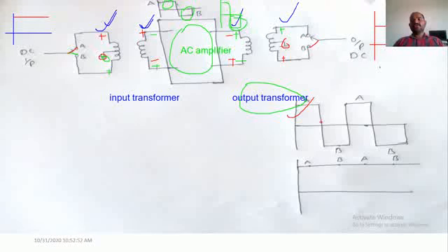So this one is called a chopper amplifier. What is the main implication of the chopper amplifier? The chopper amplifier is the one which is used for amplifying the DC signal by converting the DC into the AC, and using the AC amplifier we are amplifying the signal, and again that amplified AC signal will be converted back into the DC format. That is done with the help of the center tapped transformers which are used in the circuit. So this is all about your chopper amplifier.